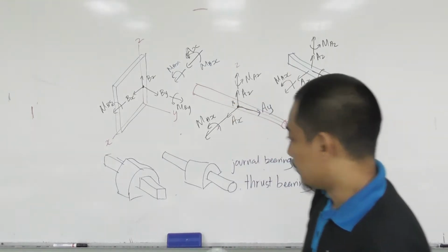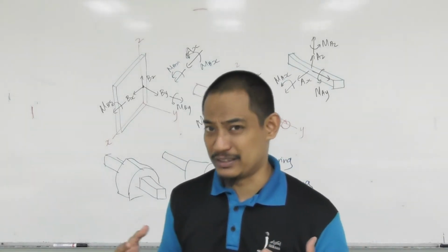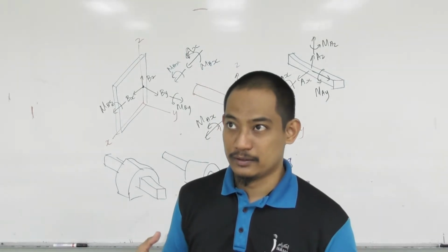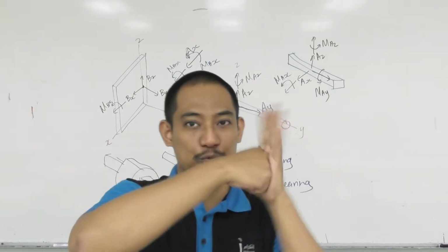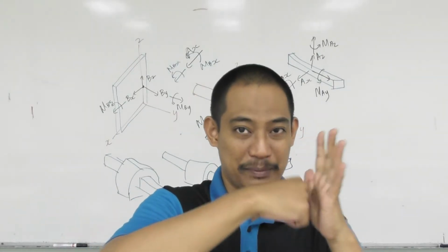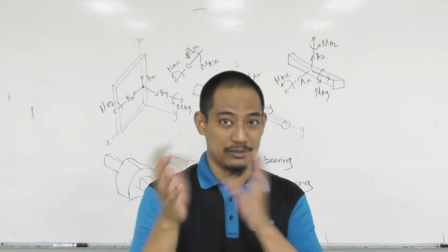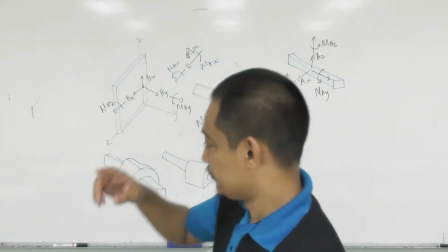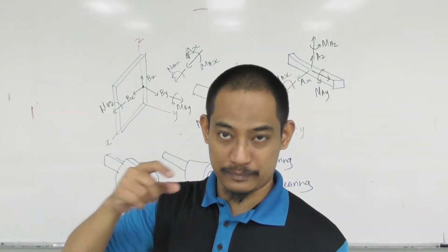All right. What else? Fixed support is easiest, right? Easiest meaning that you glue it somewhere or it's cemented somewhere. So obviously it cannot move in any axis, and it cannot rotate about any axis. Hence you will have AX, AY, AZ, MAX, MAY, MAZ, for example, right?